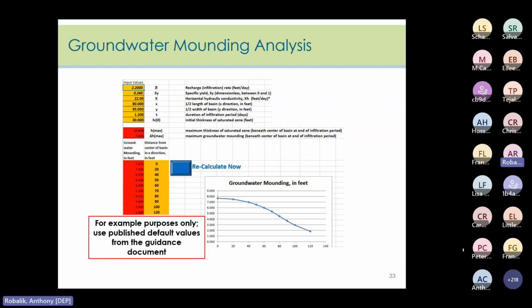So if they want to use a higher value than 10 feet, they would need to go out there and prove that, doing a continuous boring down to the depth that they're trying to use. And you have to make sure that it actually is a continuous boring, so as not to miss a small restrictive layer, and for them to prove that there are actually no restrictions down to the depth that they're trying to use.